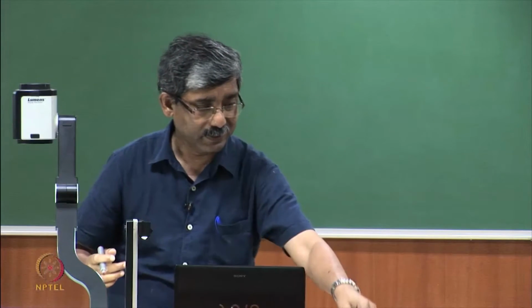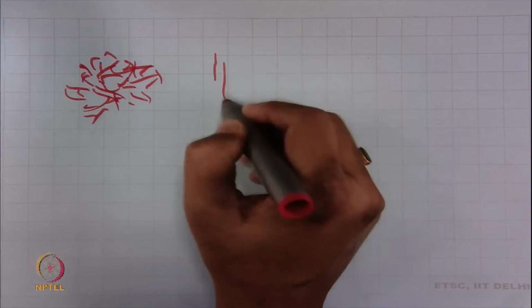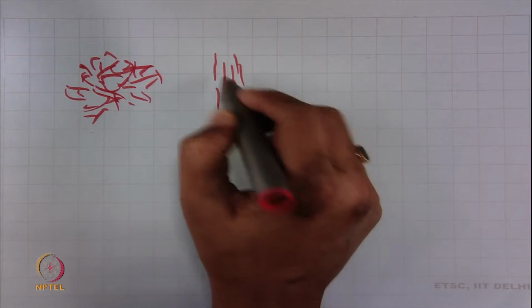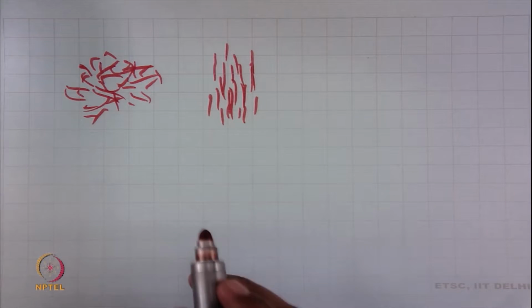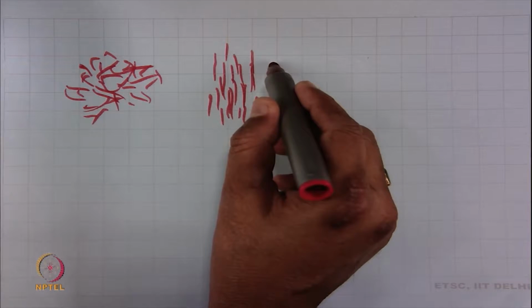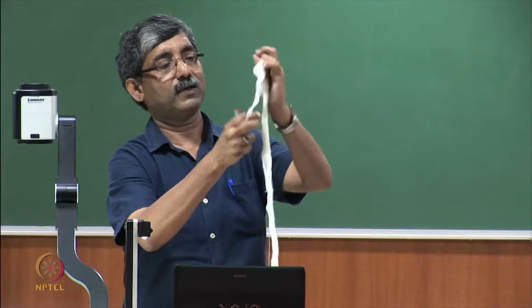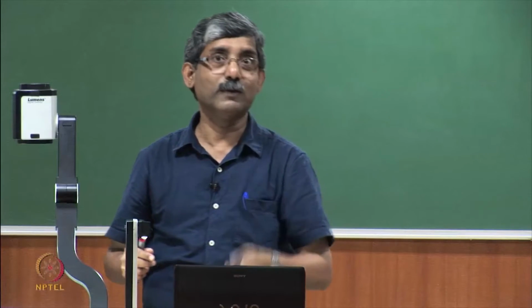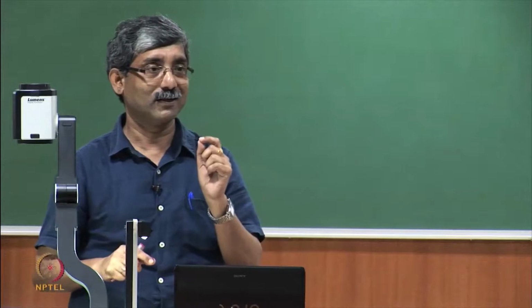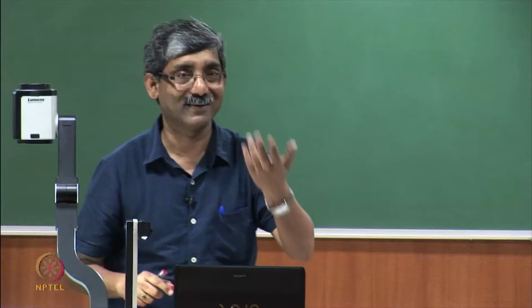But in sliver, the fibers are arranged in a particular order, say parallel. Here, if I try to pick fiber from the surface of the sliver, the problem would be that the longer fibers will have a higher probability of being selected.